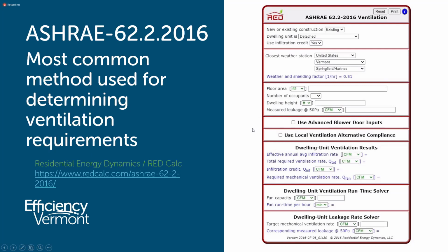So this is all very simple equations, very simple inputs. You have that data from the design documents for the building. You should be able to get this for any building easily. It's the same as the Manual J approach. You can't just go off the idea of, well, this unit from Broan says it can ventilate a 3,000 square foot house. That's the one we're going to put in. You should be getting to a little bit better detail than that.